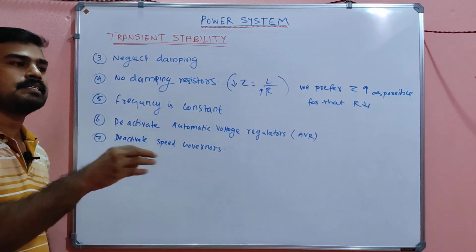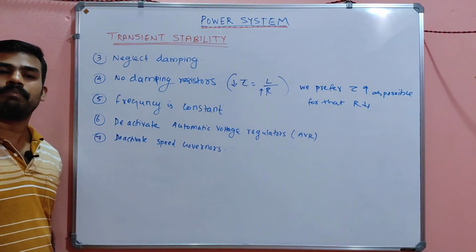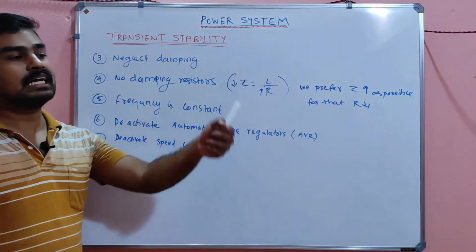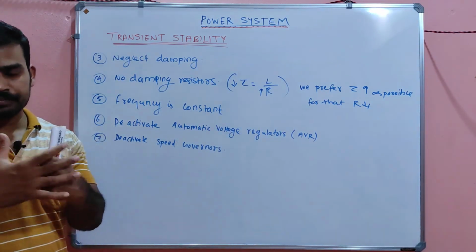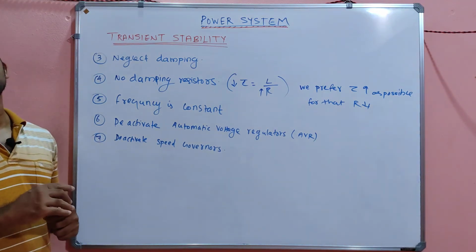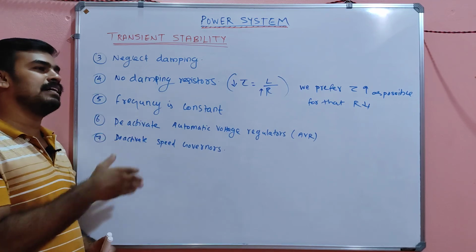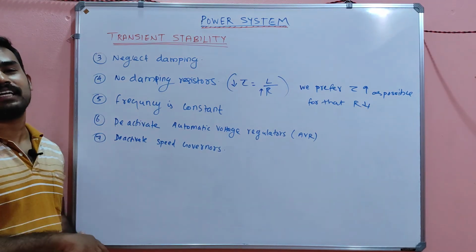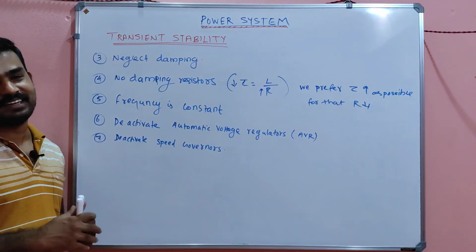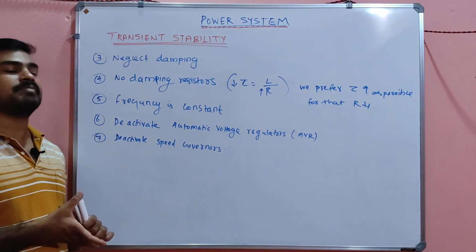If you increase the fuel input of a mechanical system, the mechanical energy will be higher, so the requirement of increased electrical energy will be matched. Like that, speed governors are a helping mechanism for stability of the system. If they are there, we won't get the worst case analysis; we will get a very stable case. So we don't want that. So normally deactivate the speed governors.